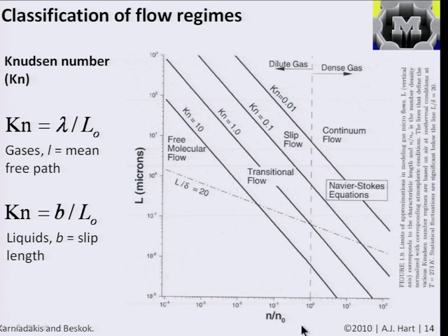That says if you're flowing air through a pipe that's 1 micron in diameter, then you have to consider that there is some slip between the fluid and the walls in order to have an accurate prediction of the flow through the system. If instead you have a pipe that's, say, 10 microns or 100 microns in diameter, so maybe think of a glass capillary that might be used for electrophoresis, then you are in the continuum flow regime, and we can, with pretty high accuracy, apply the same equations that we would have applied in regular fluid mechanics with the no-slip condition. So most micro devices under atmospheric conditions are totally fine in a continuum regime, but when we get into the nanoscale regime, we have to consider these effects when we model the flows.